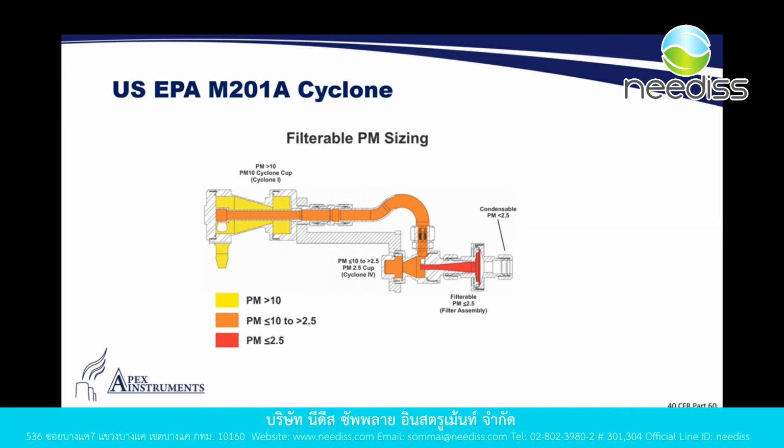It turns into dust, and it creates PM dust, just like the PM dust that we can see inside the stack. So EPA also has a method to consider that you may be missing some of the particulate that actually does come from this source, because condensable particulate will pass all the way through this particular system.